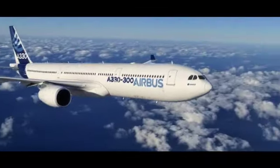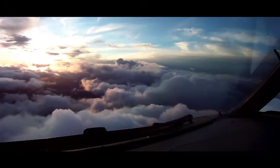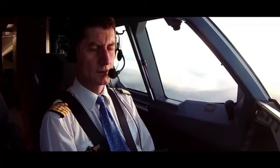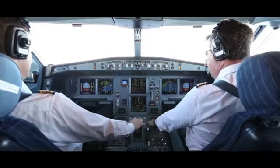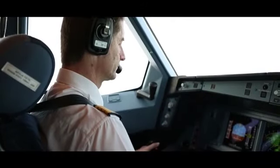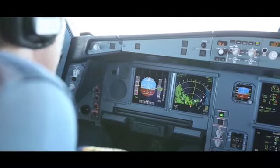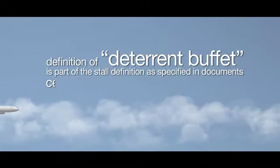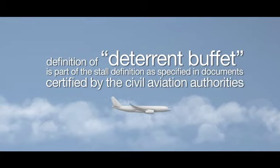So, that's the theory. But how does it work in practice? For this, we've decided to use a production A330, representative of aircraft in service. Let's start with deterrent buffet. Deterrent buffet is a phenomenon which happens at a certain stage in a stall. It is so strong that it can be dissuasive. It should be noted that the definition of deterrent buffet is part of the stall definition as specified in documents certified by the civil aviation authorities.